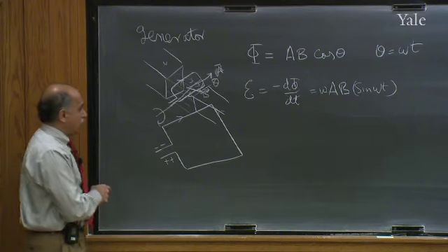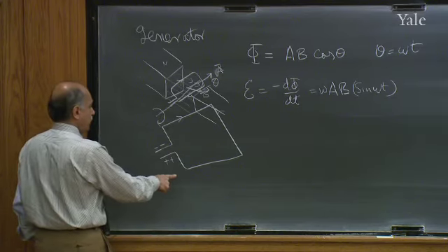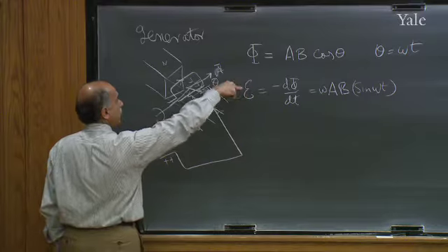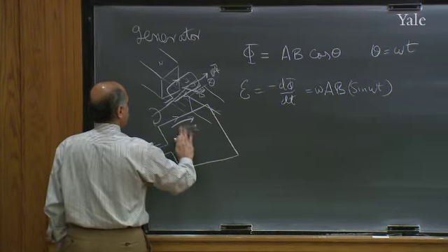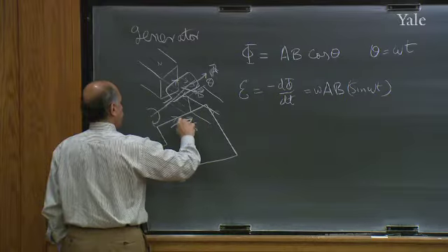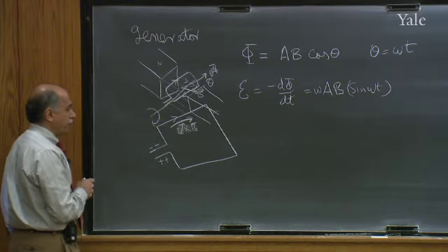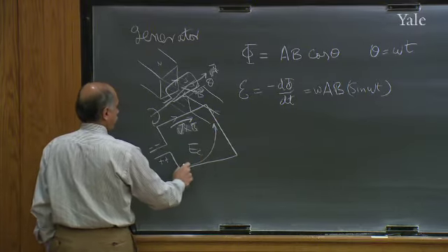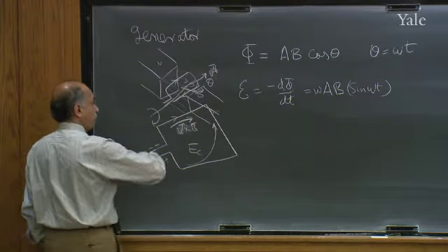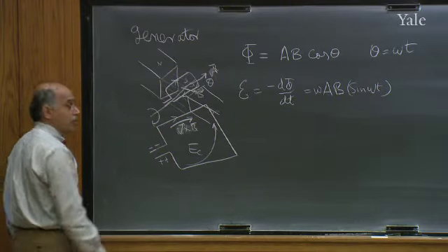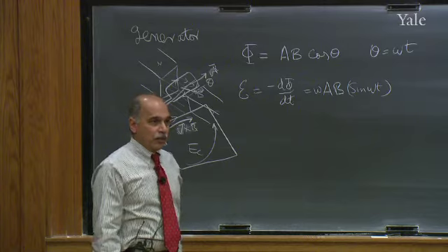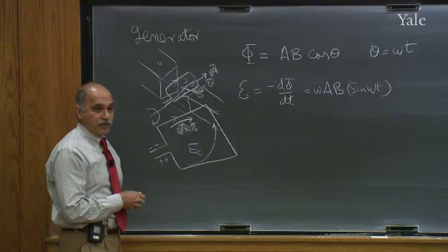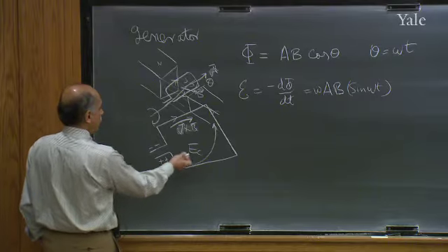At some point, these guys piled up here. So this is the induced electric field obeying that equation. This, in fact, is not an induced electric field. This is just the V cross B force on the charges. But then these plus charges will produce an electrostatic force, called the Coulomb field, which is the electric field due to charges, which will oppose it till the two cancel inside the wire. In other words, this wire is assumed to be a perfect conductor. You all know that you cannot have an electric field in a perfect conductor. You can say, hey, why do you have an electric field now?